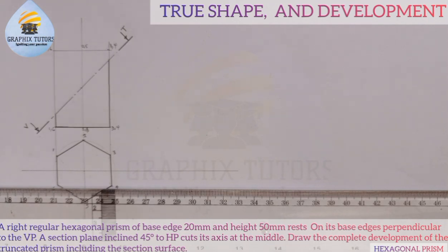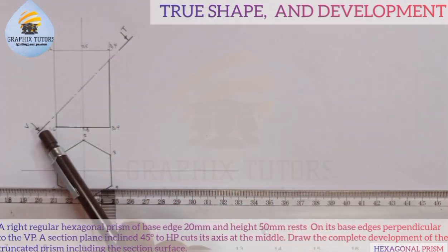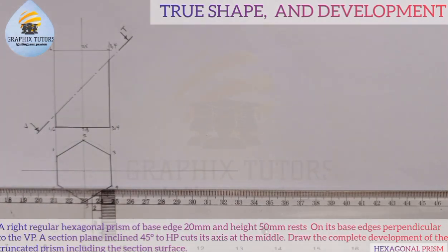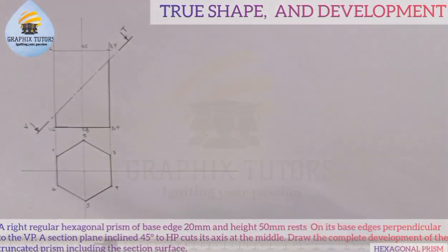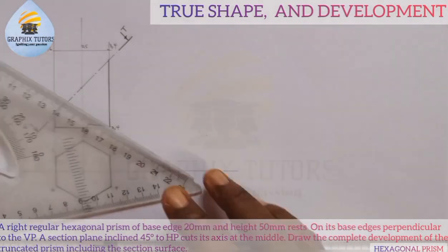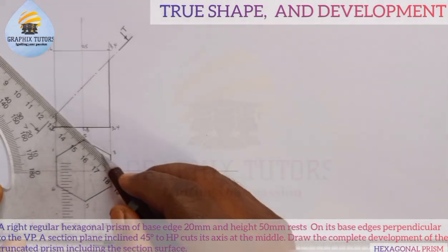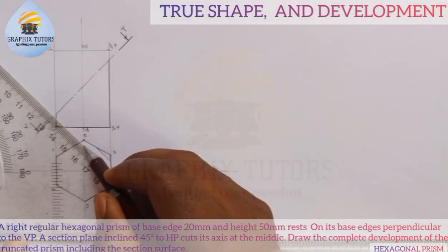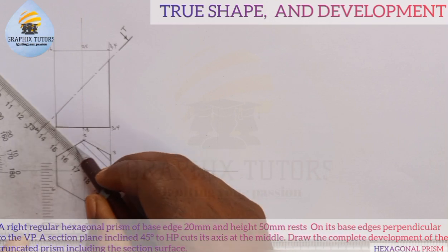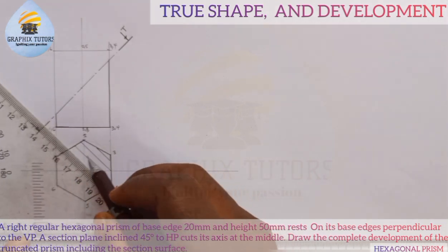Now, first thing we need to do is when you cut this off, what will you see? That is what it is actually telling us. So we want to first of all draw the true shape. And what will be the true shape when you section this part, right? So when you section this part, it means that all these parts here will be sectioned. So I'm going to close all here up this way because you've applied a cutting plane. This is what you're going to be having.